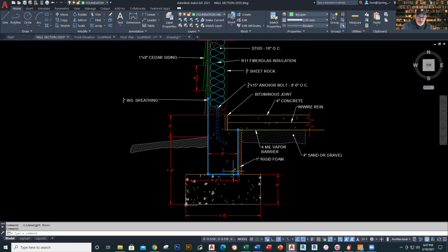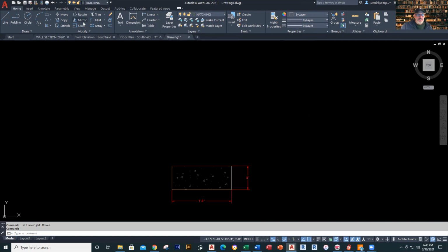So it goes over here. Try to make this clear. You've got 1 foot 2 inches, that's actually 14 inches minus 6. So it comes off here 6 inches, then goes up. So anyway, I'm going to go over 6 inches. Then I'm going to go up, and that distance is going to be, to get 2 feet, 8 inches, to get to 24, go up 16 inches. So I'm going to go up 16 inches coming off 6.